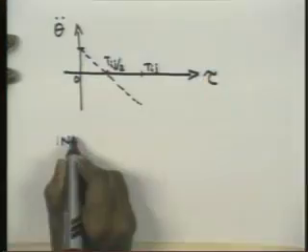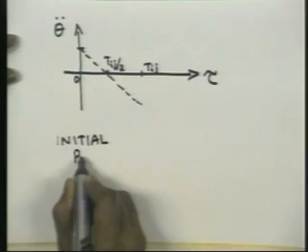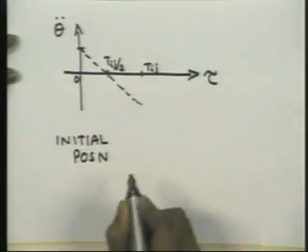If you have say n number of points through which you want the motion to be achieved, in this type of curve fitting strategy, you require that all the positions be specified, and the velocities maybe in terms of the end effector's motion, and you can do the inverse kinematics to calculate the joint space velocities through the kinematic relationships. Okay, but somebody has to specify all the velocities at all the points. So, just imagine how this strategy will be implemented in actual practice.